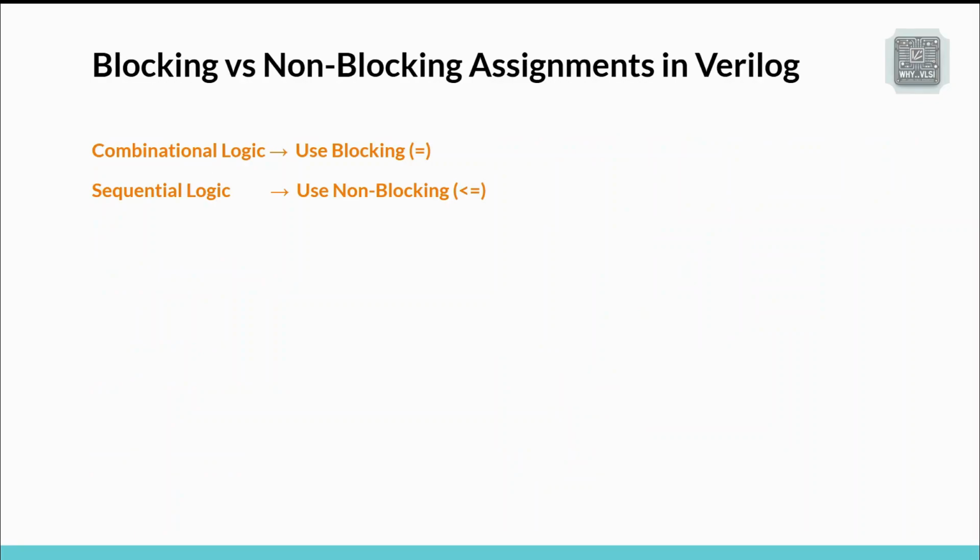To avoid this issue, RTL designers follow a simple rule: blocking assignments should be used for combinational logic and non-blocking assignments should be used for sequential logic, such as a flip-flop. Following this guideline ensures that simulation behavior matches hardware implementation.